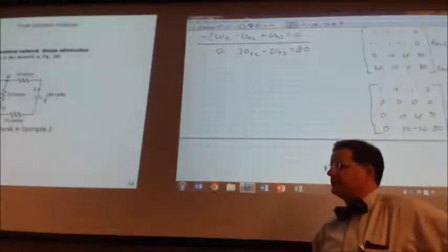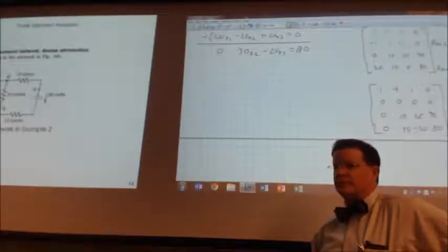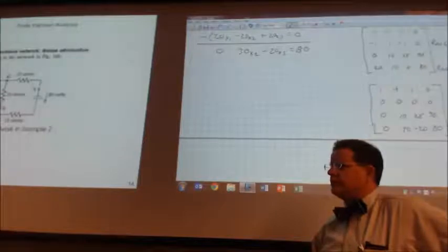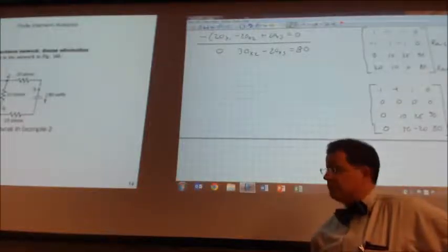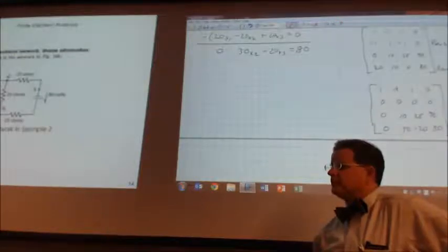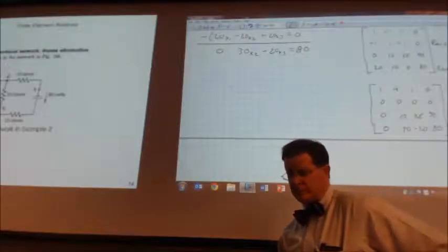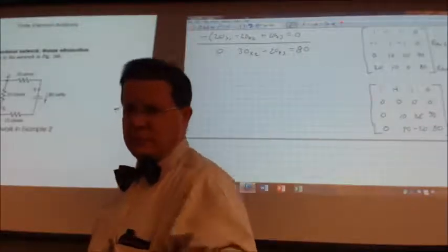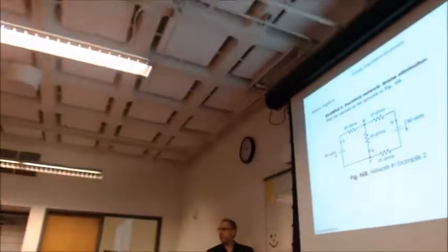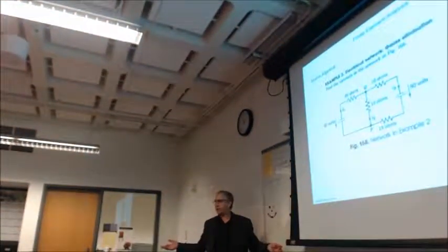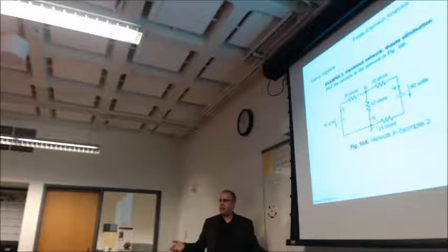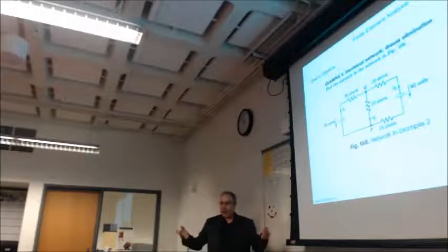The trouble is, it's in a direction. And you know that wood is not the same in each direction. Nobody splits wood against the grain, right? Why? Because it's not the same. So it's anisotropic versus isotropic, isotropic being the same in every direction and anisotropic being not. So it's all screwed up anyway. In fact, every time you get a material, a piece of melamine, an extrusion, all the grains are smashed going that way, so even then the modulus can be stiffer that way than transverse. It's just a matter of how screwed up it is, and do we have to worry about it? And if we do have to worry about it, how do we worry about it?